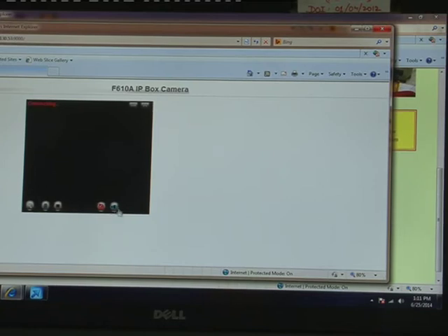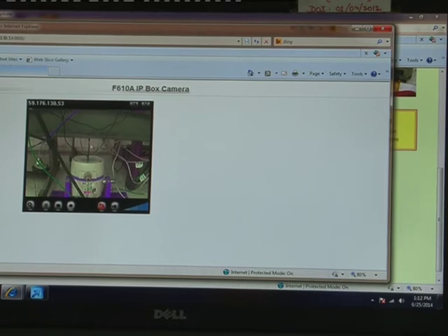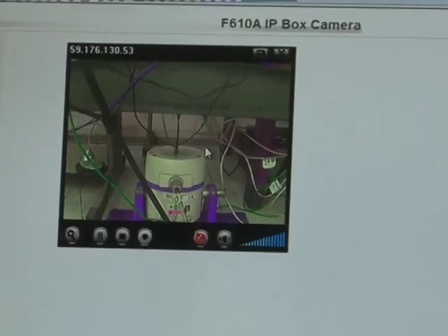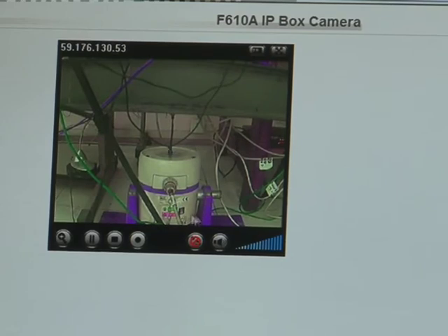For experiment 3, I will switch on the sound so that you can get the real time feeling of performing the experiment. Here you can see the shaker, it is connected to the bottom flange of the beam. The snoring sound which you are hearing is being produced by this shaker, as we have given a sweep frequency.